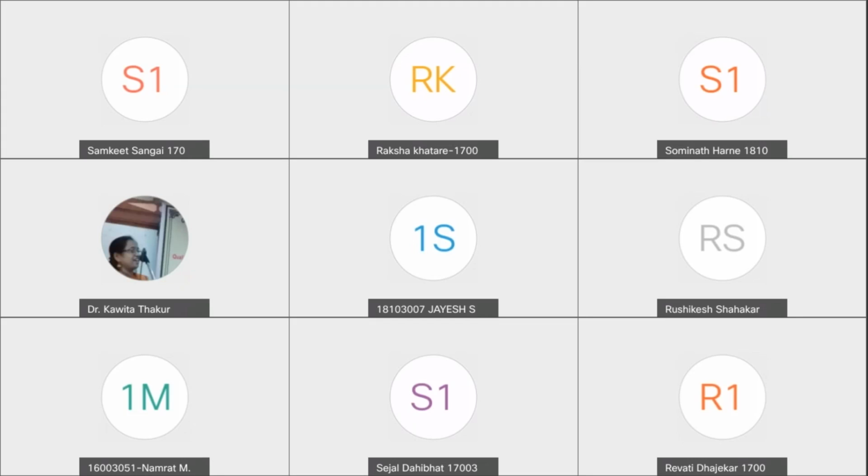It provides high sensitivity and high selectivity. Differential protection is a unit type protection for a specified zone. It is very sensitive to faults occurring within the zone of protection and less sensitive to faults occurring outside the protected zone. There are two types of differential protection, current and voltage. In the current differential scheme, there are two sets of current transformers connected to either side of the equipment, and the ratios of the current transformers are so chosen that the secondary currents of both current transformers match each other in magnitude.